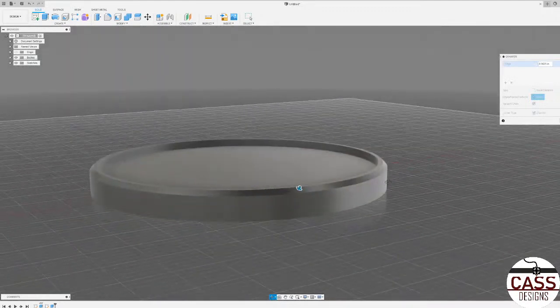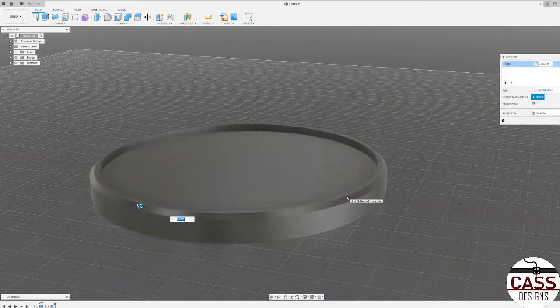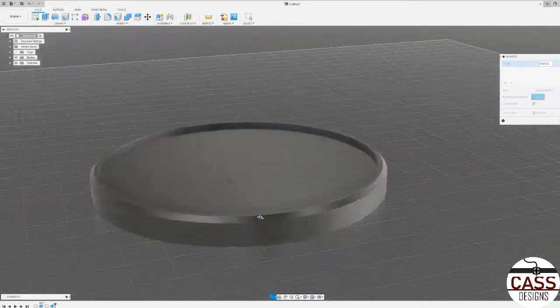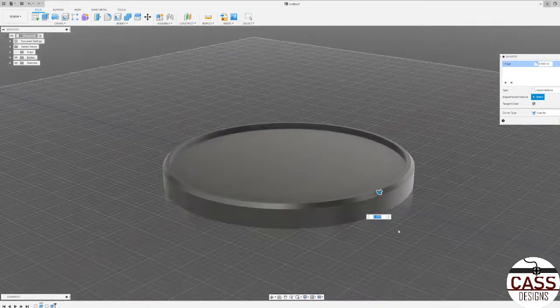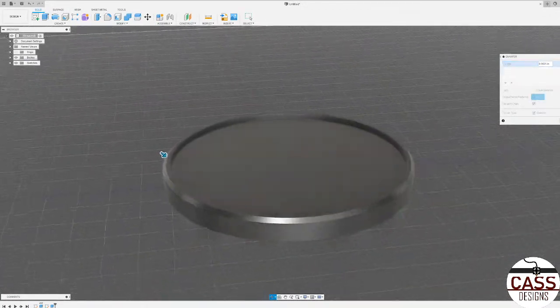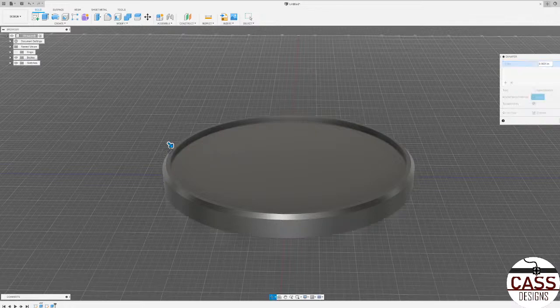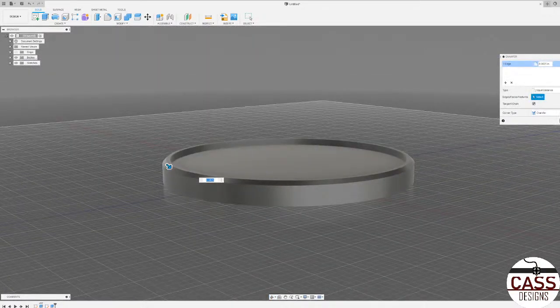And the purpose of these is if you don't want sharp edges. If you want rounded, you use a fillet. If you want it not rounded and kind of slanted like this, you use a chamfer. And that's what this does. In design for actual tools and fixtures, and in the real world, people use chamfers for screw holes, so the countersunk screws have something to grasp onto and are flush with the surface that you're screwing into. But that's the point of a chamfer.